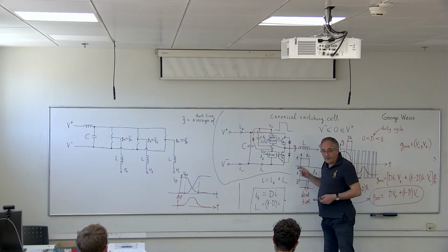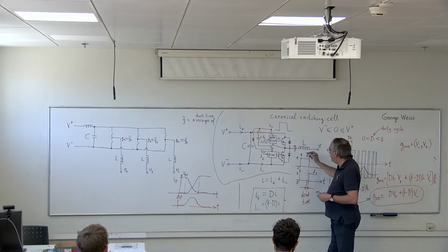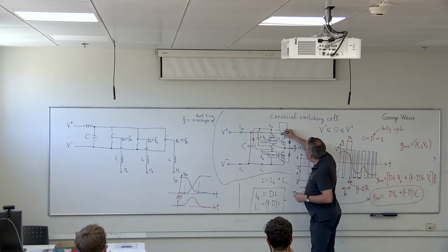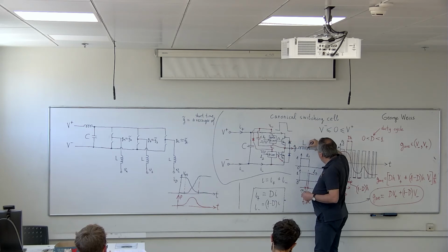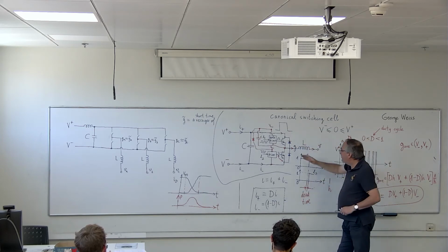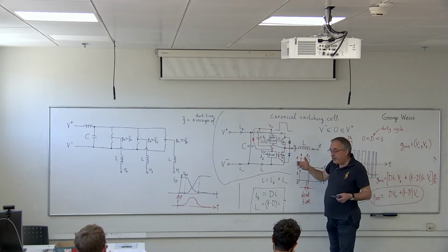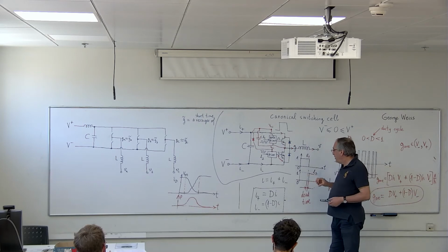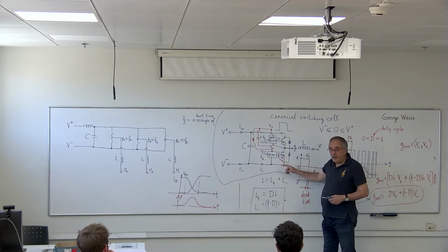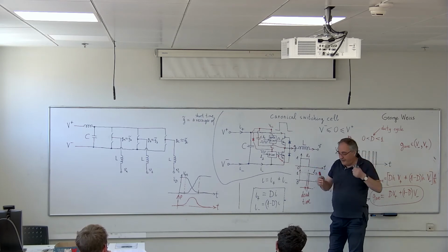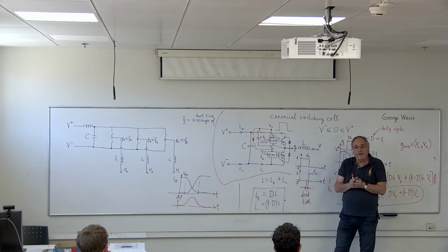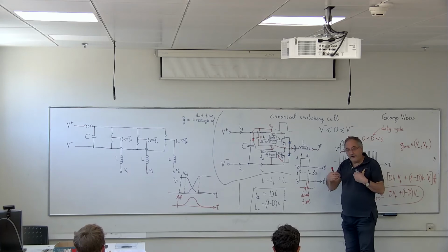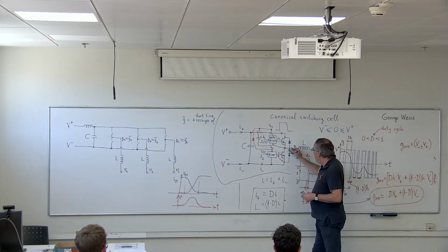That's where the diodes come in. Because let's say that you have a current flowing in this direction, and it came from here. So it came from here through this switch and goes out here. Yeah? And now you want to switch it. You want to stop this switch from operating, so you want to switch it off, and you want to switch on the lower switch. So you give a dead time. So you have switched this off, but you have still not switched on the lower switch. But you cannot stop the inductor. The inductor will create a huge voltage if you try to stop its current. So the inductor demands the same current also during the dead time. So where will this current come from during the dead time? It will come from this diode.